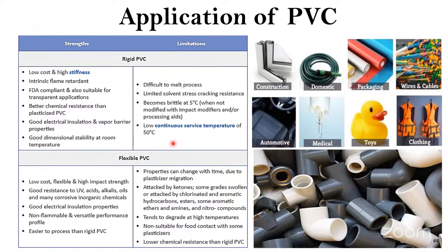The plasticizer will come above your PVC and they will give you different properties. That is the reason in our research world, we do a lot of study on the plasticizer, how not to migrate to the surface. It should stay inside the material and give that effect. So plasticizer migration is a very big challenge.